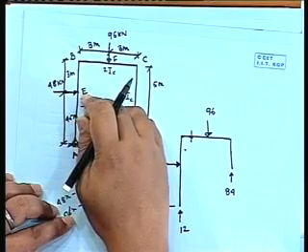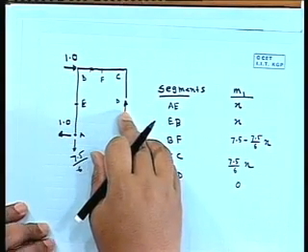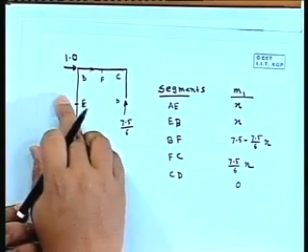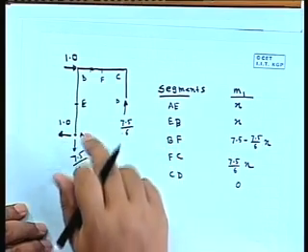right. Now in that way we can find out deflection at any point. Say our structure was this one, this is the basic structure. Now here we have given 1 unit load. Say if we are interested in getting the deflection here, so we have to take the structure and just put 1 unit load there, find out the reaction, and get the expression for bending moment under that situation.